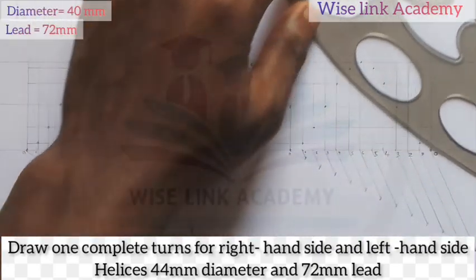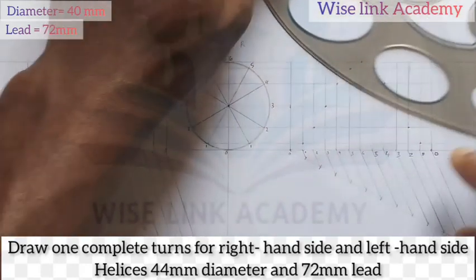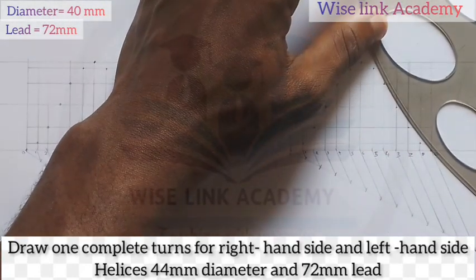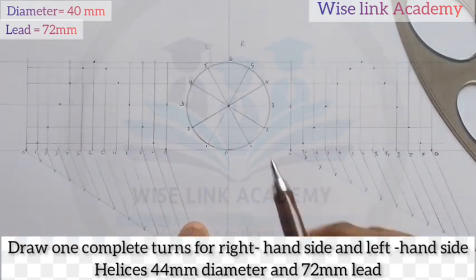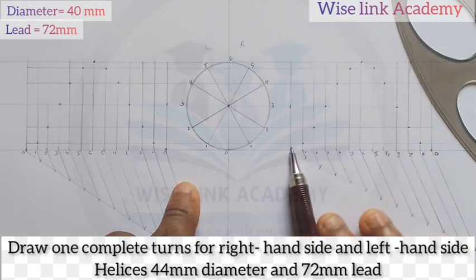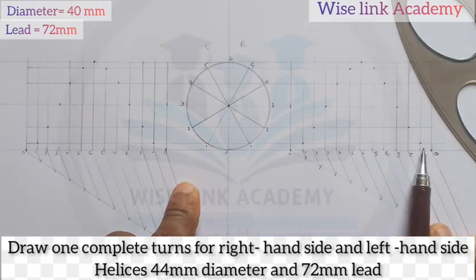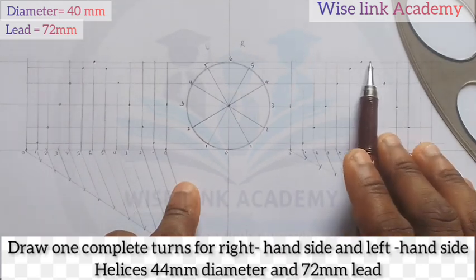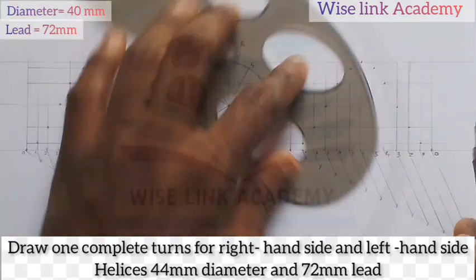Let me connect this first. Let's take it little by little. I connect these points. Now listen. If I look at this stuff this way, I'll be seeing this very well, but I will not see this part. So I will make sure this part is drawn with a dash curve. So let's connect this first together.